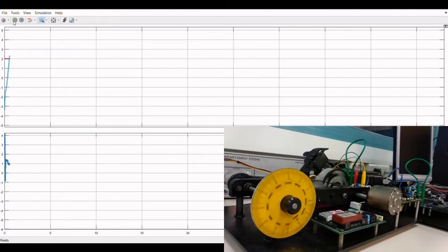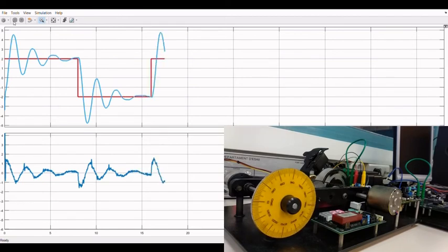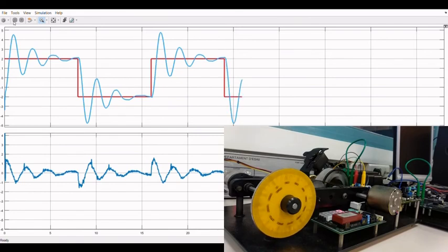In this video we can analyze the system's behavior with the shown IPD controller, where the reference varies from -2 to 2 volts. The control has been designed such that the system has an 80% of overshoot and a natural oscillation of 0,5 Hz.